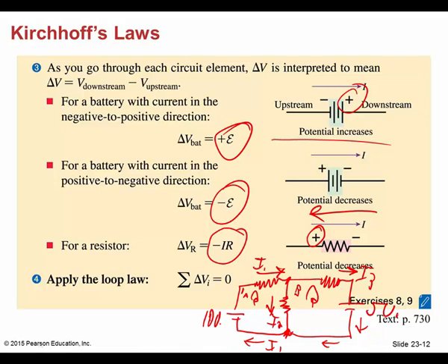So my current equation is I1 equals I2 plus I3. All right, that's my current equation. Then we have to start going around our loops. If I start here and go clockwise, like I said, and come all the way around this loop, let's say that's 3 ohms, this is 2 ohms, and that's 4 ohms.